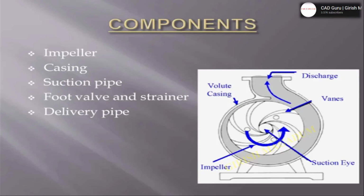And you could see, as I said, this part will rotate, and this is the suction eye. From there the water will be sucked inside, and these are the volute casings, wherein more pressure head will be created due to the particular shape of the volute. This is the discharge and the impeller. As you could see, the same thing here, the explanation about each and every component.